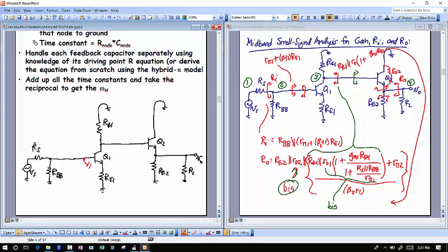One of those capacitors is going to be C pi of device 1. Another is C mu of device 1. And another capacitor for device 1 that I'm going to include is the CCS of device 1, just for the heck of doing it. Sometimes it's important, sometimes it's not. I think your book ignores it quite a bit, but I'm leaving it in so that when you go to 140 next semester, you'll use CCS every now and then. Those are my capacitors for the first transistor.